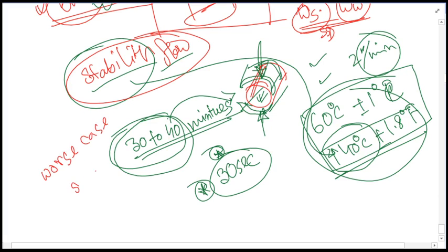As you all know, the problematic factor for bitumen is nothing but the water. So while it is submerged in the water, it will be exerting the poorest case you can expect from bitumen, this bituminous specimen. So that's why we'll be submerging it into the water for 30 to 40 minutes within this temperature as well.